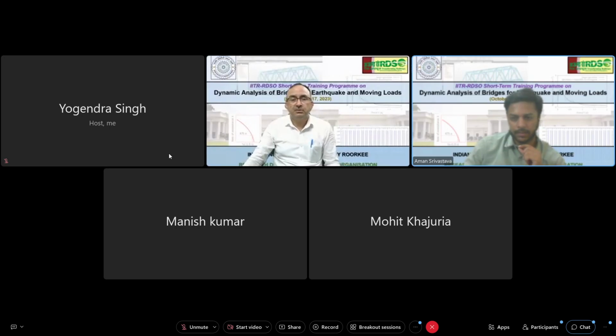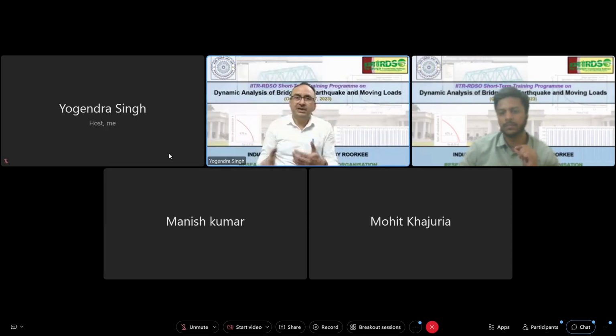Okay, sir. Mr. Abhishek is asking, while doing time history analysis using already recorded data, how is the intended lifetime of the structure accounted for? Okay, so the intended lifetime of the structure we are taking into account in the return period of the earthquakes, that is, the probability of occurrence we are taking. For example, in the case of buildings, we are considering, let us say, 10% in 50 years. In the case of bridges, we are considering 5% in 75 years. So that changes. Whatever period we want to put, 50 years, 75 years, or 100 years, that is going to give us a higher target response spectrum. And when we select the ground motions corresponding to a higher target response spectrum, we will get higher intensity, and probably higher magnitude and closer distance.